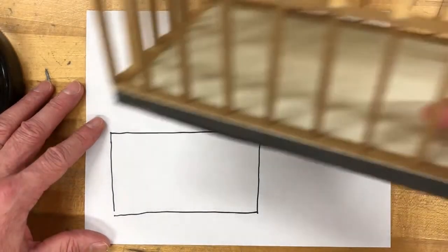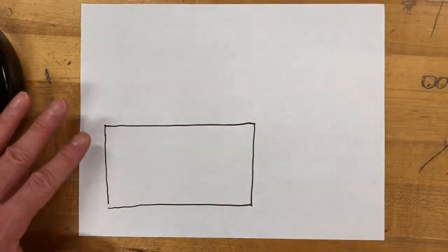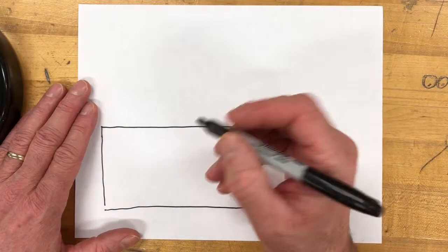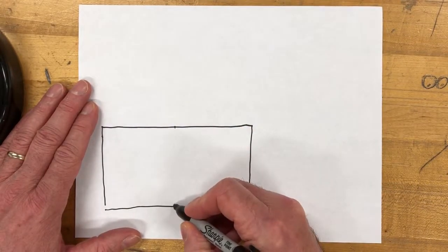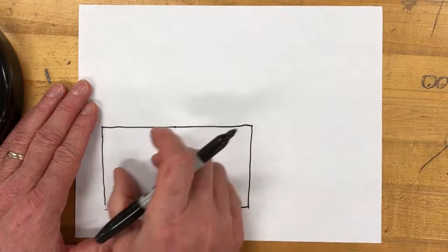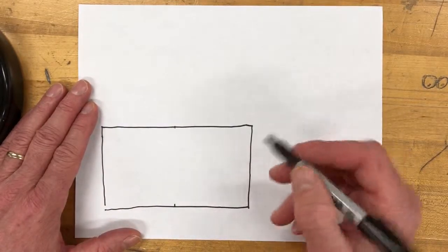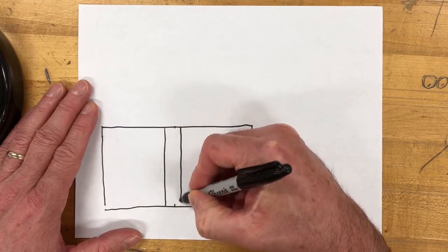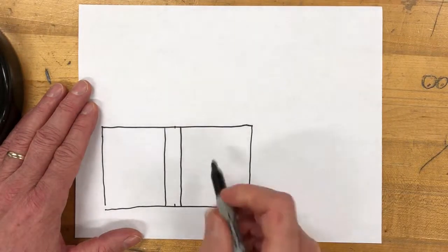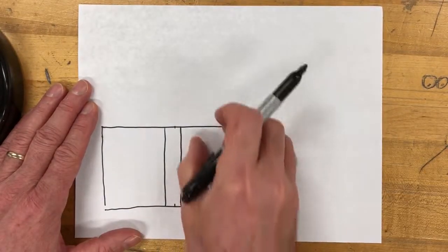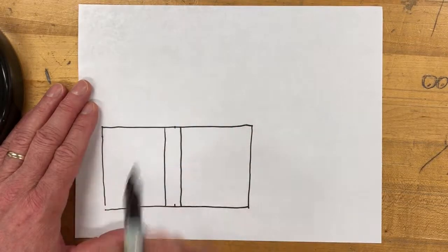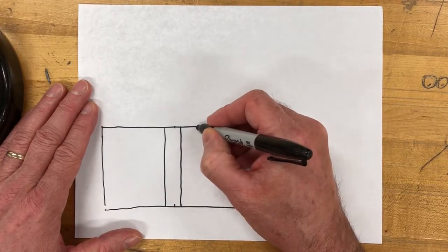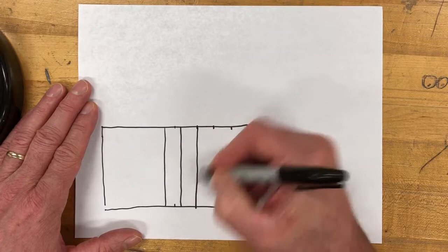Now, as I said earlier, we've got this MiniBarn, and we need to figure out 9 stud pockets. The question is how do we draw that out on the paper? The easiest way I found to do this is to identify the midpoint, just like that, on either side. Then I start thinking about, what if I had to divide this into 9 equal pieces? I would estimate what 1/9 of this might be, and then draw this right here, just like that, around the midpoint. What that does is it leaves me 2 open spaces, with 4 stud pockets here and 4 stud pockets here. That's really easy. All I have to do is divide that into 4, just like that. And then I draw my lines down like this.